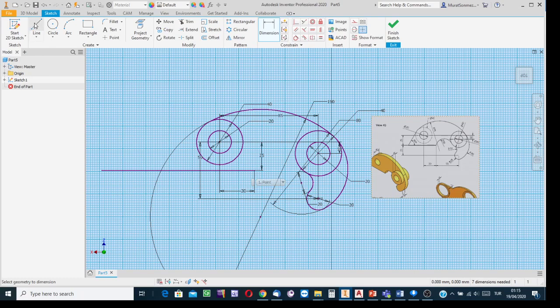And then you can create the other line. First create the line arbitrarily on the correct side where we are going to have the tangent line. Create it longer than its order of magnitude. Press escape and then the constraints. Dimensional constraint: indicate this line, indicate the other line.